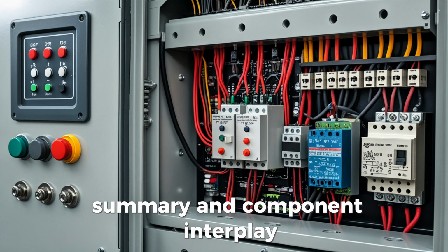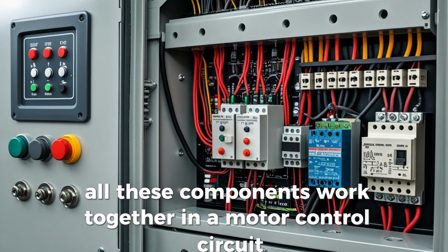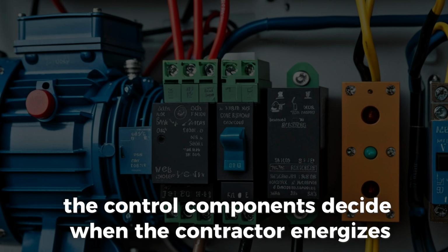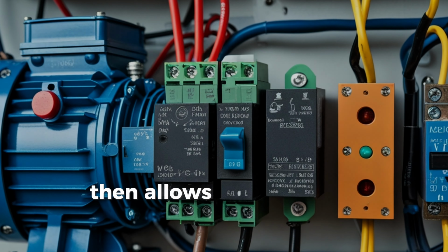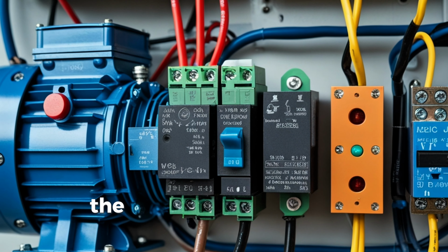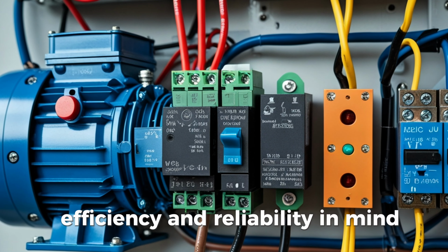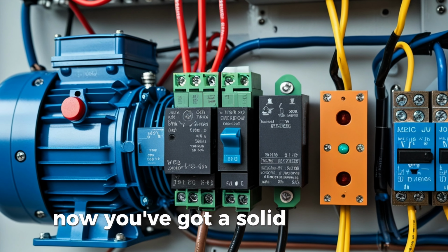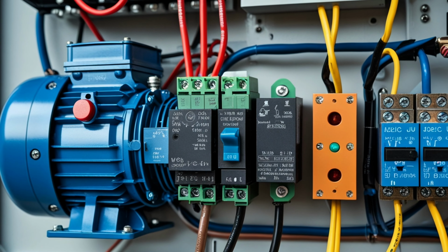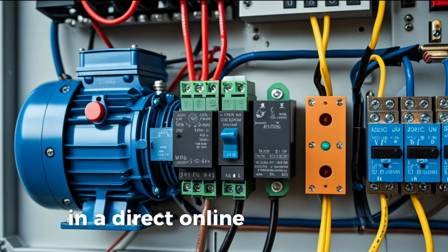Summary and component interplay. All these components work together in a motor control circuit. The control components decide when the contactor energizes. The contactor then allows power to flow through the protection devices to the motor. The entire system must be designed with safety, efficiency, and reliability in mind. Now you've got a solid foundation in the basic components used in motor control systems. In the next video, we'll look at how these components are wired in a direct online starter circuit.